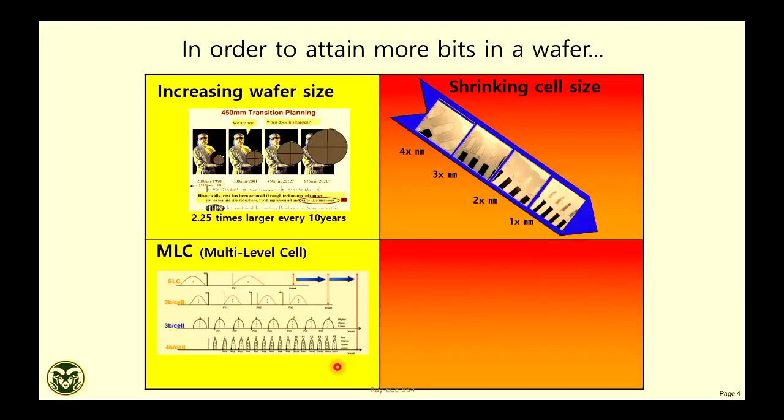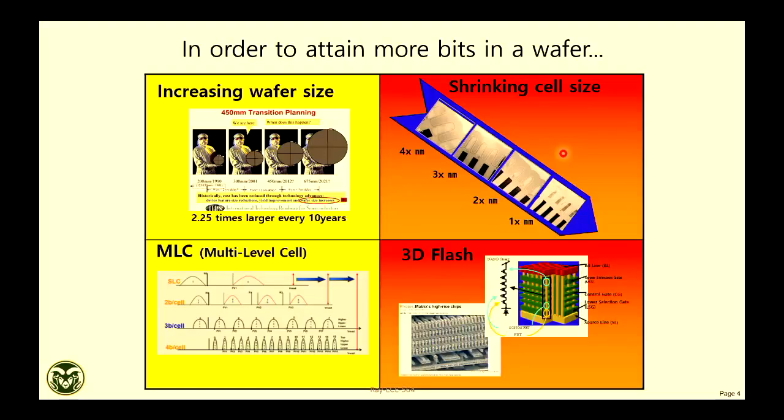What else can you do? You can logically scale, you can physically scale. What else can you do to increase your bit density? That's why the topic is 3D NAND. You can make it taller. Tall is the new small now, right? Earlier you made things small so you could have more bits. Now you make them taller. You are effectively packing more bits, because at the end, as a user, we care about footprint. If you have a tall building, then every floor is bits that you can pack, right? So for a given footprint, you increase bit density by making things taller, or by monolithically growing, right?